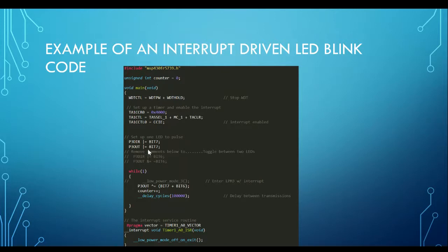Port 3 direction, bit 7, is being converted into an output pin, and the value of the output pin has become 1. So if you connect an LED to pin 7, it will light up.